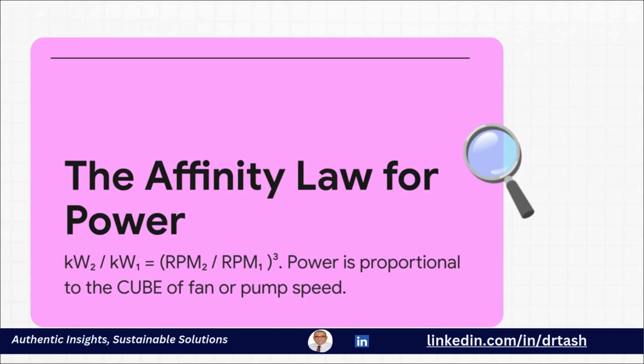Okay, if there is one equation you absolutely have to have in your back pocket, it is this one. The Affinity Law for power. It's so powerful. It tells us that the power draw of a fan or a pump is proportional to the cube of its speed. It's not linear. It is an exponential relationship, and that changes everything. It's literally the entire reason VSDs are such a game changer.